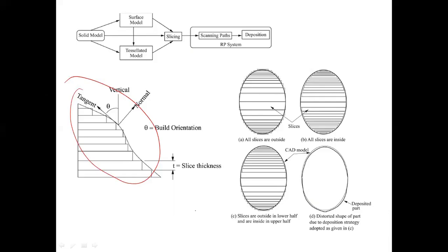The part has a specific layer height, called the layer thickness, LT. Theoretically, you can define every layer thickness individually in order to get the profile. This is the profile that I want. Based on this profile, a number of layers have been plotted.